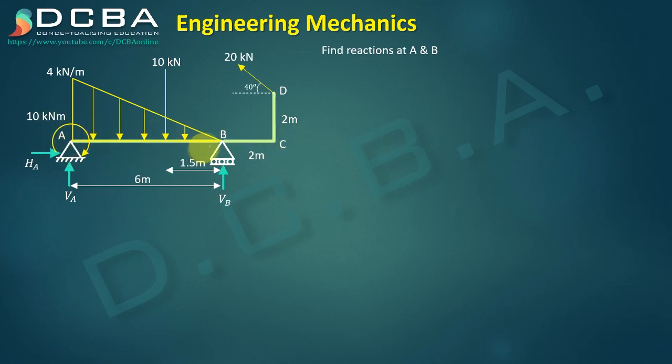And then there's something different in this numerical, that is we have this extension of 2 meters and a force of 20 kilonewton inclined at 40 degrees acting at the end of the extension, right? So again, before finding the reactions, we need to consider the entire system to be under equilibrium, and only then we'll start finding the reactions. So we need to apply the conditions of equilibrium. The conditions of equilibrium would be the same: summation Fx, summation Fy, and summation M equals 0.